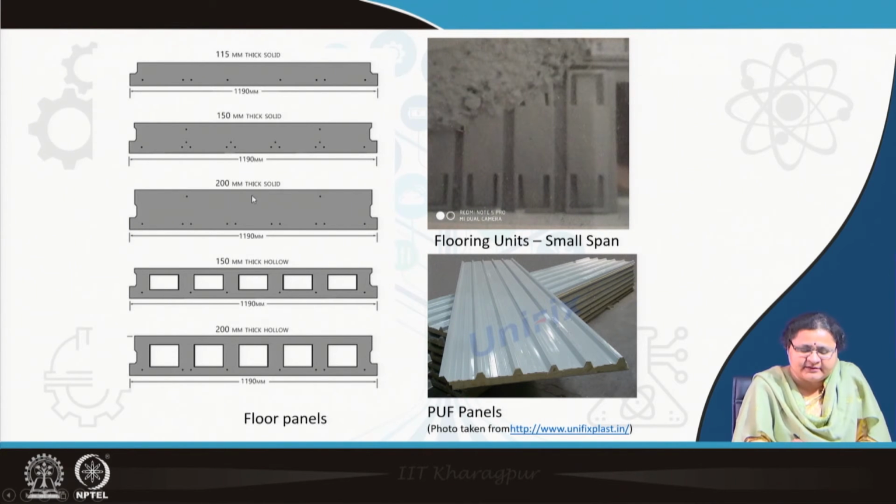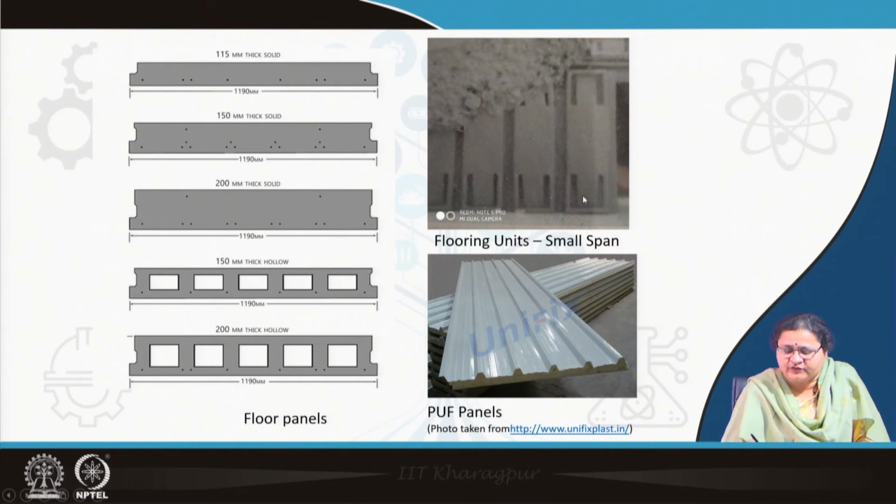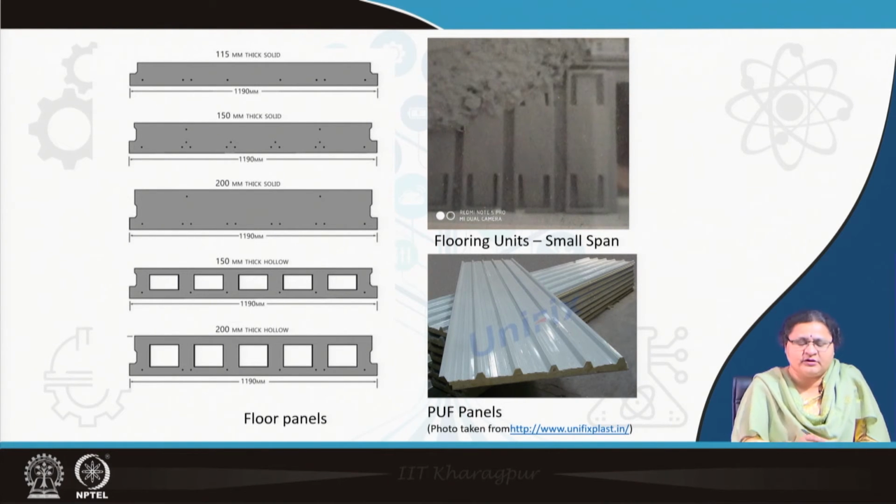In this case the flooring unit as you see in section is flat. Here you see there are lots of notches. So, on top of it concrete is filled in to make the floor flat or usable. These units are for small spans, and these units are for large spans. By this time you are almost thinking that everything is of concrete.